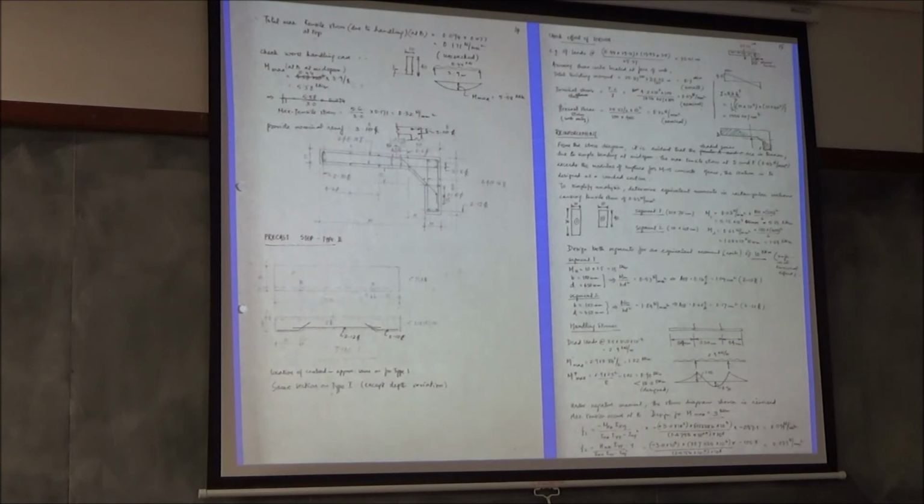We actually cross-checked with each other. They're all faculty, so we got this mutual support. So lots of studies were done. Then another thing, we have to also tell them where to put the hook to lift the step, because in transporting it can get damaged. So we have to plan the hook location. So construction stage activity also, so you can work out the bending moment. We want to make these two more or less equal, and then design it so that we make sure the reinforcement is adequate.